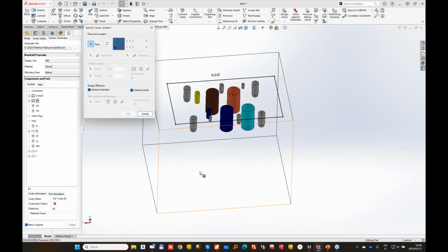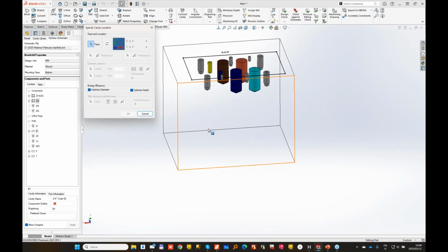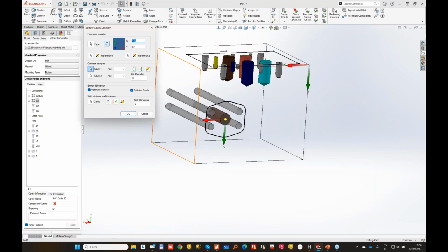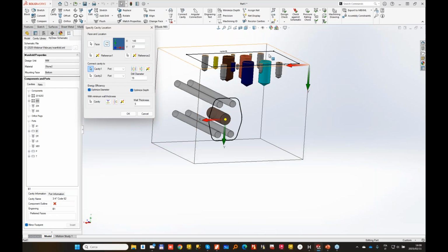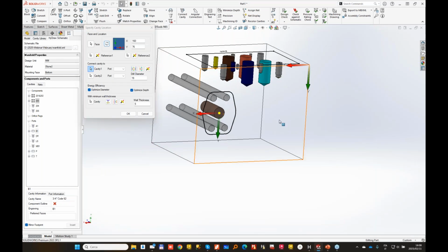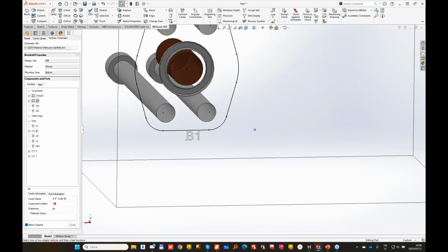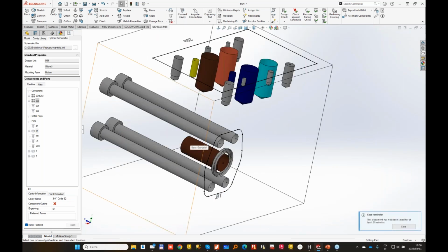And when I click OK, now MDTools is asking to place the footprint on the block. So we can see a preview with the true bolt holes. I can rotate my bolt hole. I'll try to position in the center. That was 180 millimeter, and let's leave as is now. When we click OK, now MDTools will place the flange with the opposite bolt holes and also with the engraving in a better position than earlier. Now let me save my block.